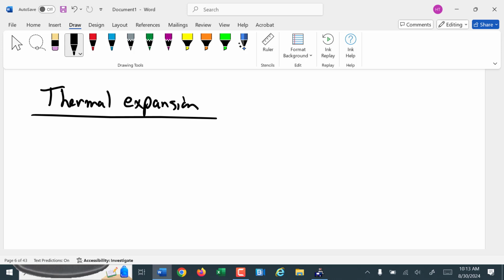We're only dealing with the range of temperatures that humans might be able to survive in. Most of your machines are not going to operate a lot above that temperature because the room temperature has to be survivable for the operators. But with steel, for example, somewhere around 930 degrees, it actually shrinks for a second. It starts to contract.